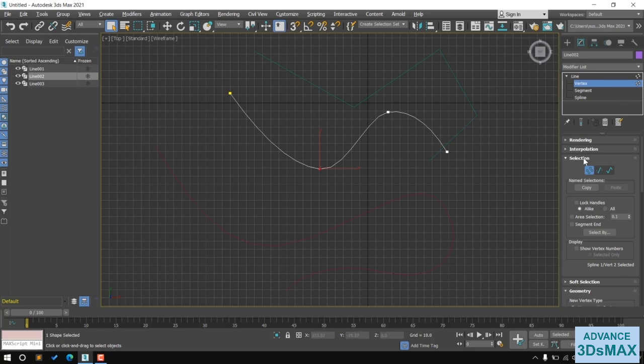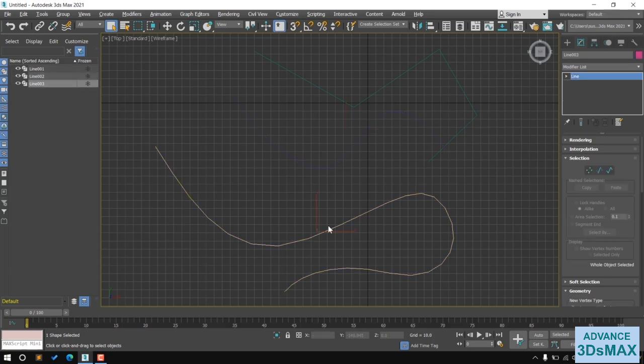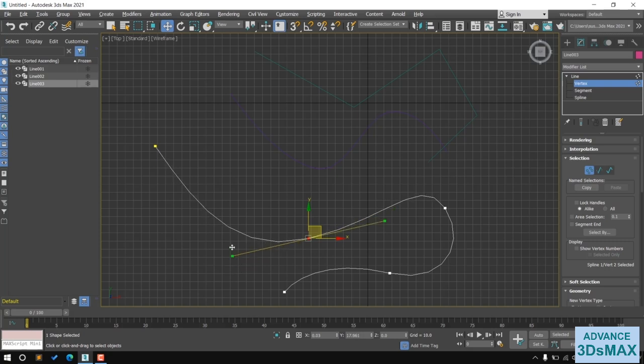To edit this modification, click on this icon. So you can select another object. And this line we created by using the Bezier method. So if I choose the vertex, you can click on the arrow and expand this. You can select from here or also here. If I select this vertex, these are handles. So this is the difference between Bezier and smooth line. You can control a Bezier line by using these tangent handles. Okay. I click on this vertex icon to exit the modification process.